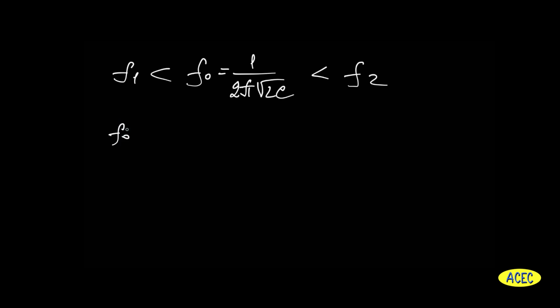Now let's analyze all these due to vector diagrams. It helps us to understand everything clear. In first case, in case of resonance, when frequency of the input signal generator has the same value as resonant frequency, we will have the following situation. Voltage of resistor and current in the circuit will be on the same axis because resistor is active load. Then reactive voltages, which have phase shift of plus 90 degrees and minus 90 degrees respectively, will have the same value. Respectively, total reactive voltage is 0.